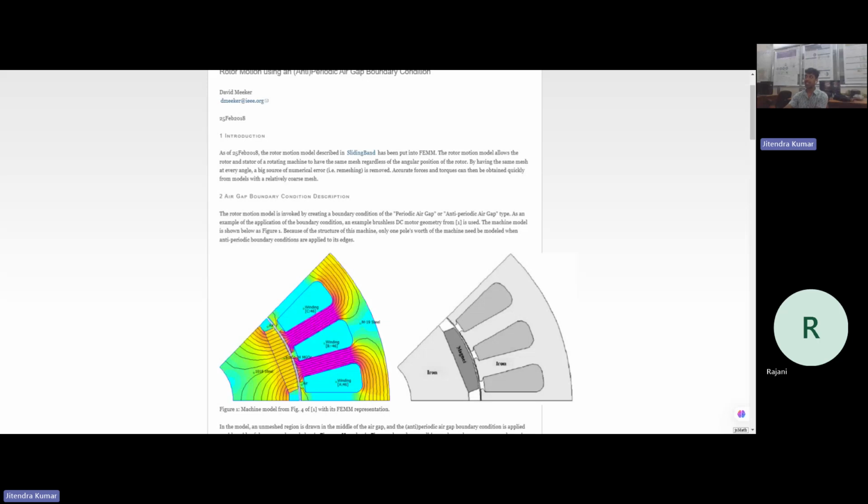Yes. But in Altair, it's a little hard work. You have to create volumes, define the volumes, and check every step. Then only can you go to the next step. Geometry is okay, then only you go to mesh. Mesh is okay, then only you can go to physics. Physics okay, then you can go to the solve scenario. There are a few more steps added, but it's a very convenient software. Anything we can do over there.